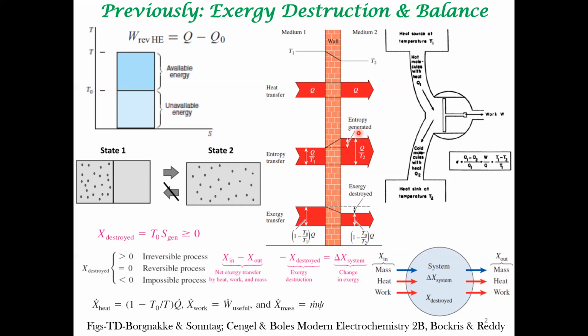And then we looked at entropy balance for the simplest system. After setting up the equations, we start looking into how to apply these equations to certain systems. So we looked at the closed system, the simplest system, and there can be different ways of transferring Exergy. As Exergy is a state variable, you can associate Exergy with a particular mass, or heat transfer or work transfer.